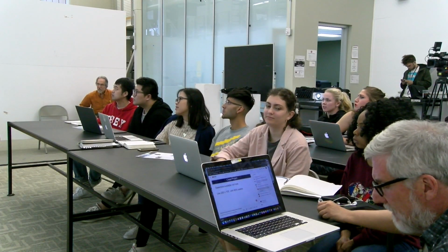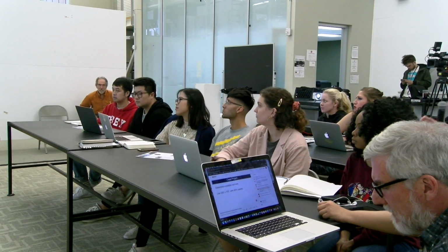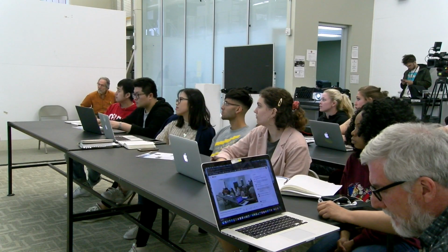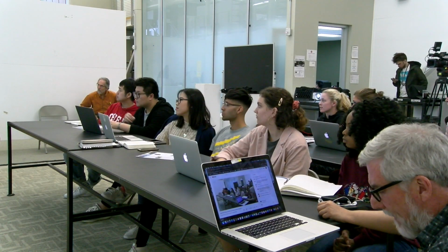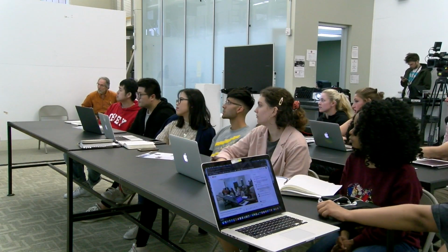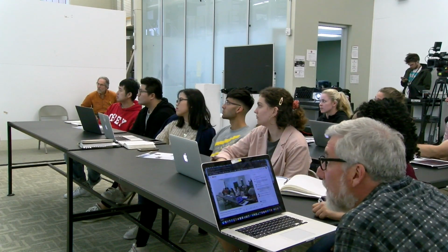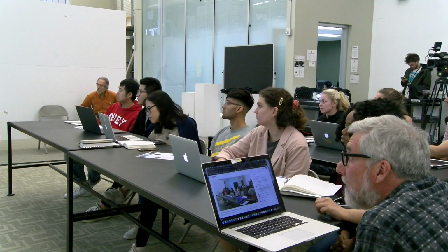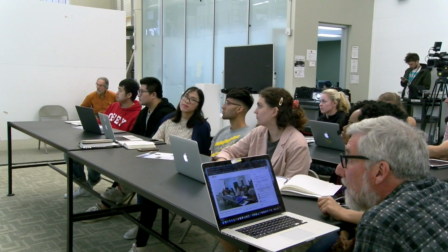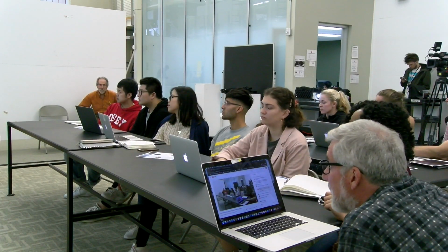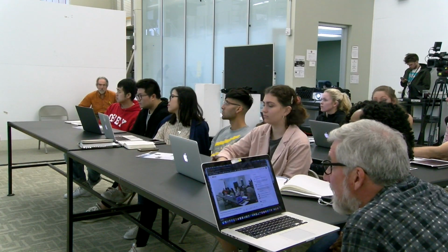Why do you think I'm using 80% of the roof? I mean, you have 100% of the roof. We're literally measuring from edge to edge. But is all of that usable for solar? No, some of it is utility. What do you think would be lost? Why would not all of it be used for solar? What would cut into that? You need to access the roof. There are access lanes, fire setbacks, parapet walls, shading. Shading is the enemy of solar. Again, this is on average. You can't use every square foot, so that's why I'm making a rounded estimate of 80%.